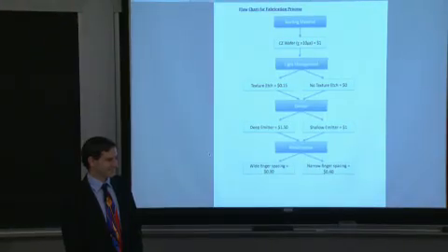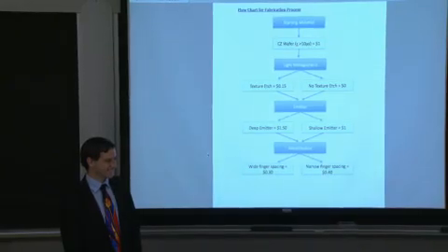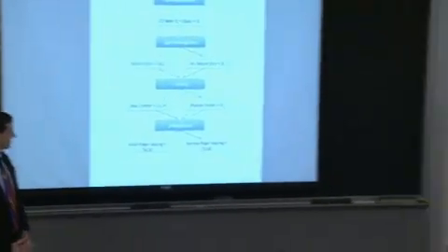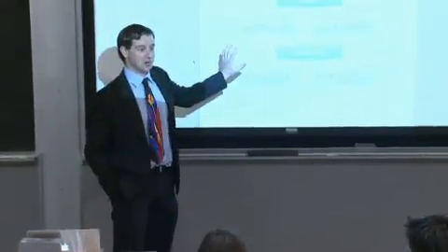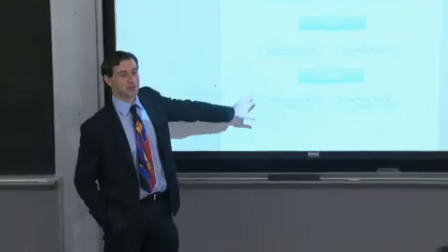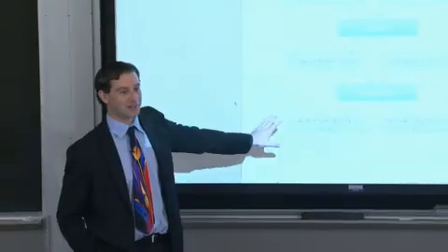I mean, this is meant to be, yeah, you're not going to get exact answers. But you can do your best to estimate series resistance from the finger spacing and your emitter thickness. Believe it or not, you might feel like you don't have the tools right now to get good quantitative answers, but you do. You have a number of the tools here to get, say, 90% of the way there. In engineering, 90% of the way there is well beyond what you'll actually face in the field. So that's pretty good.